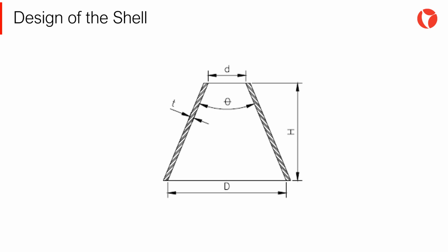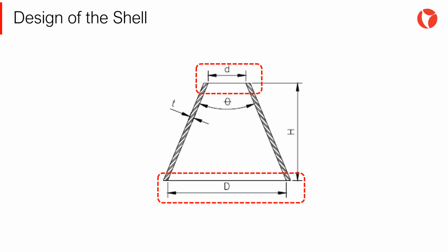Once the required cone thickness due to internal pressure has been calculated, the cone to shell junction must be evaluated. If the conical transition doesn't have knuckles, there is a stress discontinuity in the cone to shell junction, mainly due to the effects of internal pressure and axial loads, caused by the self-weight, for example. These loads could overstress the area.